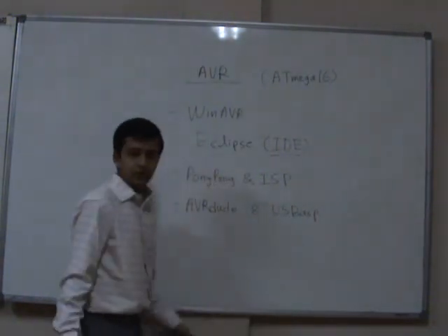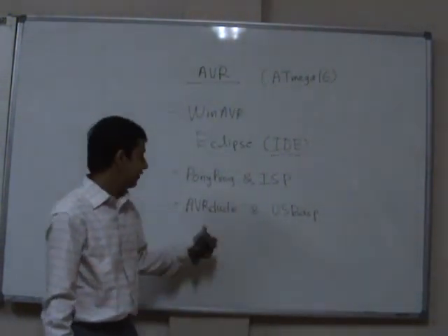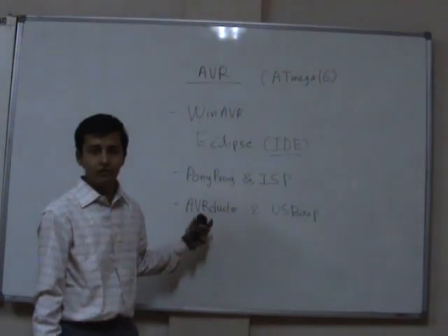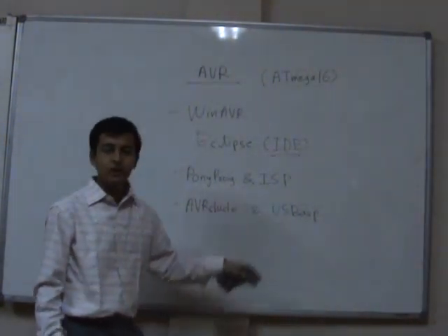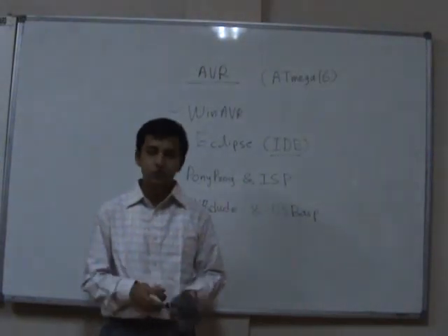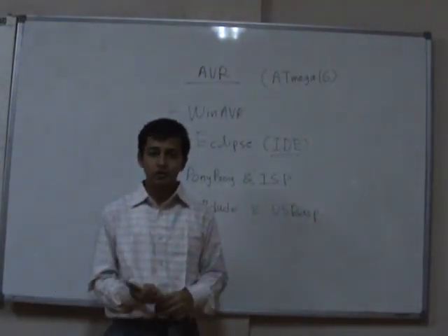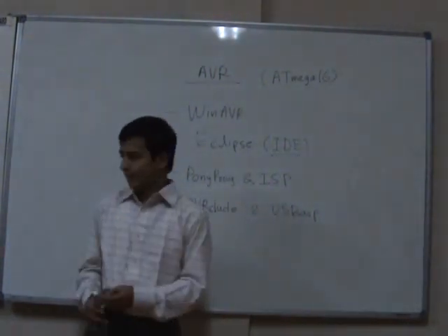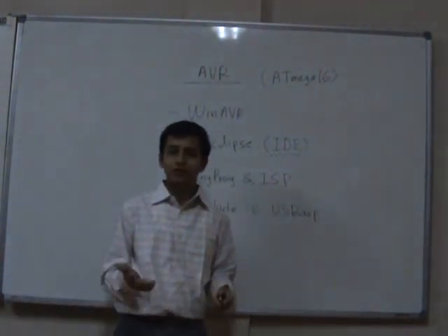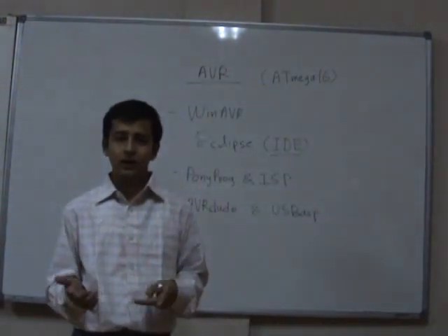USB ASP is the USB based AVR programmer, and AVR Dude is the command line software which we will use to burn the files into the AVR. USB ASP is basically a good choice because nowadays none of the laptops have serial ports or parallel ports. So I would suggest you go for USB ASP. And obviously you need some breadboards and wires to try things out quickly on your own.